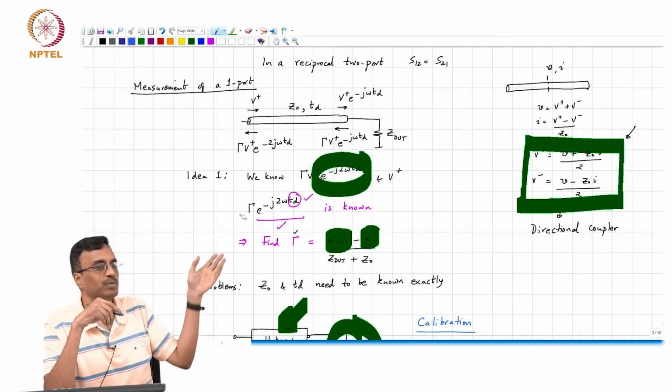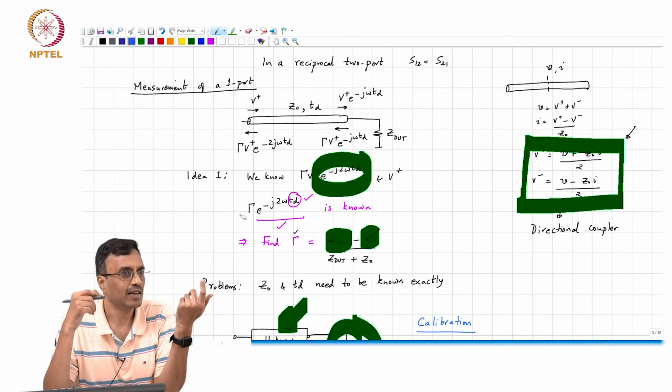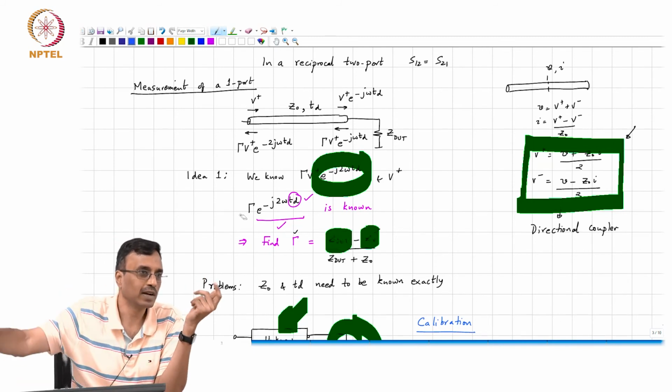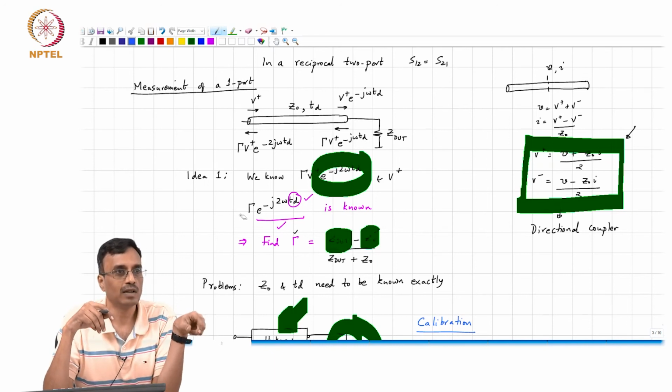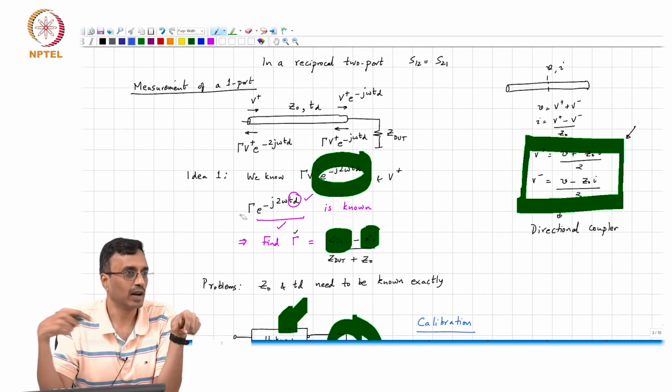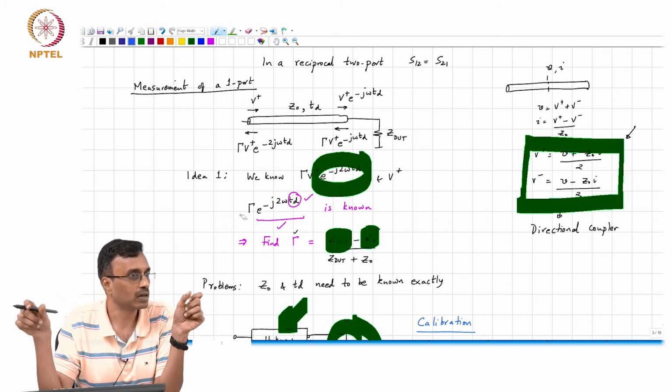Of course, if your cable has some finite resistance, then there will be an error, right? To fix that error, if you want to be really careful, you terminate the other end of the cable with a short circuit and see what you measure on your multimeter. Then you connect your unknown resistance, and the difference will give you the actual resistance that you want to measure, correct?